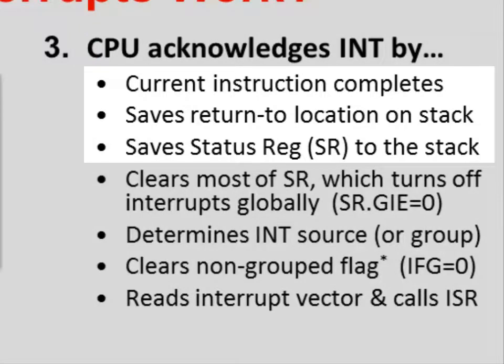First, we hope that the first 3 items on this list are self-explanatory. The current instruction is completed while the program counter and the status register are written to the system stack. By the way, the system stack is set up by the compiler's initialization routine. Please refer to the compiler user's guide for more information about the stack.